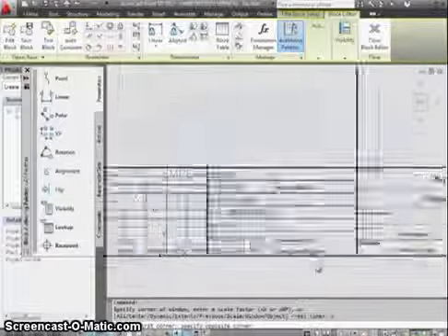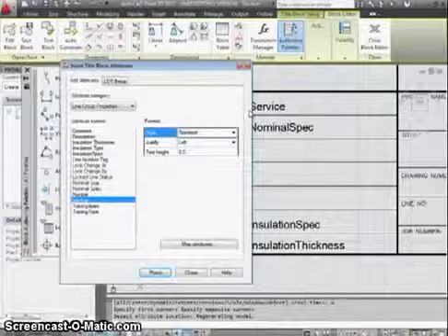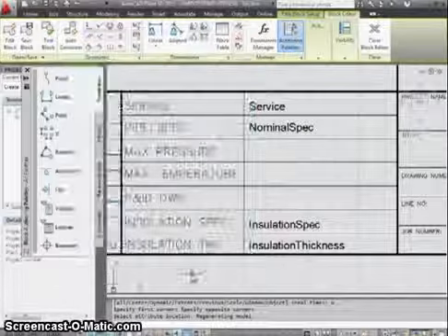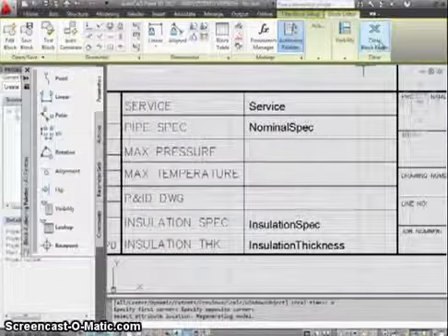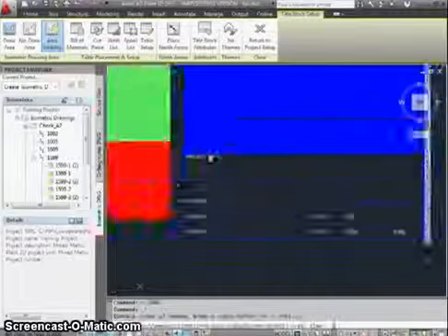You can also create your own attributes because this is just a regular AutoCAD block. You can modify it in the block editor or replace it completely. So let's close the block editor and save the new attribute to the title block.